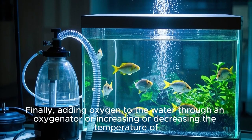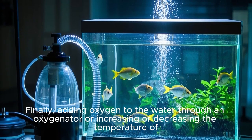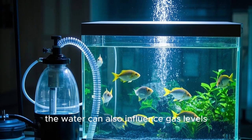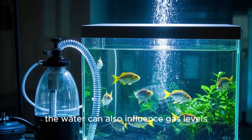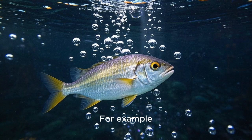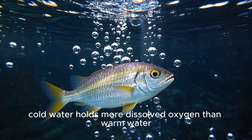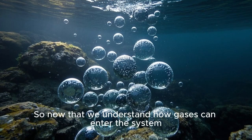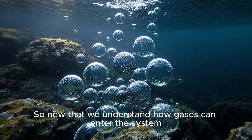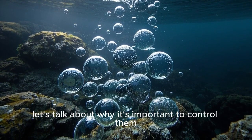Finally, adding oxygen to the water through an oxygenator, or increasing or decreasing the temperature of the water, can also influence gas levels. This is because the solubility of gases is temperature dependent. For example, cold water holds more dissolved oxygen than warm water. So now that we understand how gases can enter the system, let's talk about why it's important to control them.